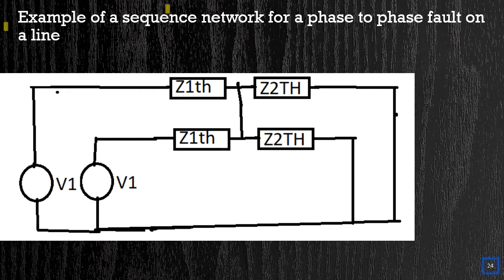It is good to understand sequence networks. However, without software, it can get very tedious to have to calculate a solution by hand. For this reason, in my opinion, it is much more important to understand the general dynamics of sequence networks than being efficient at performing hand calculations. Short-circuit software is an incredible tool that should be taken advantage of. But without understanding the underlying principles, it is hard to fully take advantage of the tool or to fully understand a system's characteristics.